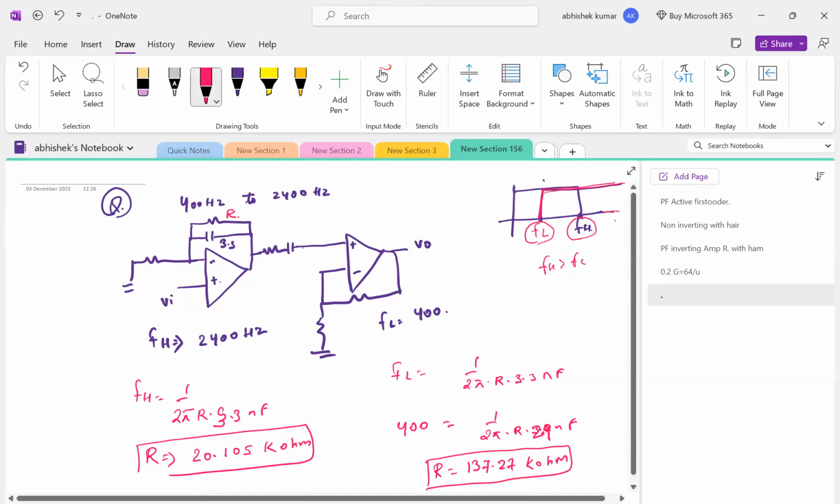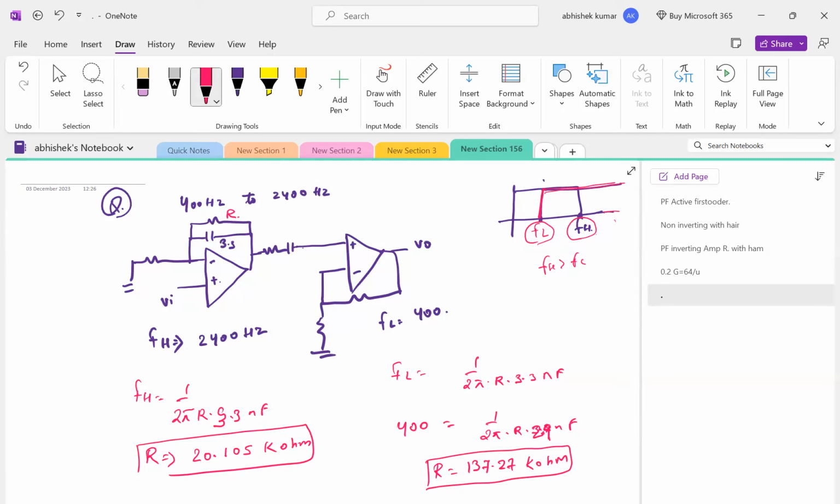What we have to understand is, earlier for low pass, we had a cutoff. Low pass will always have the high cutoff. You have to make it clear, because it is the maximum frequency after which the signal is not getting passed. That's why we denote it with FH. And for high pass, it is the lowest frequency after which the signal is getting passed. Are you getting it? When we do it individually, we reverse the names, correct, FL and FH?